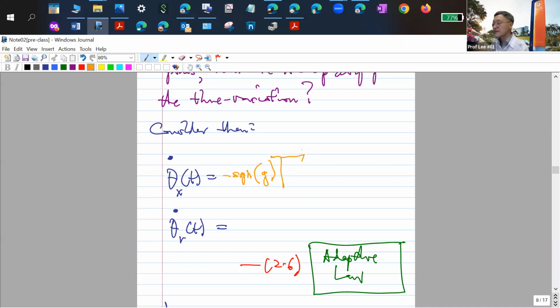If you don't really know how to choose your capital gamma, you can still choose gamma 1 as in the first order case, and make it gamma 1 times the identity matrix. If you take gamma 1 times the identity matrix, it will be positive definite as long as your gamma 1 is positive, and the identity matrix is symmetric positive definite, so that will also be okay. But the full symmetric positive definite matrix is helpful because it gives you more flexibility than just gamma 1 times identity. But that will also work.